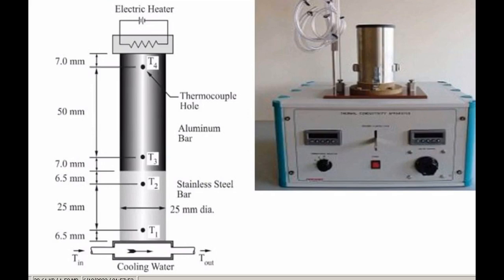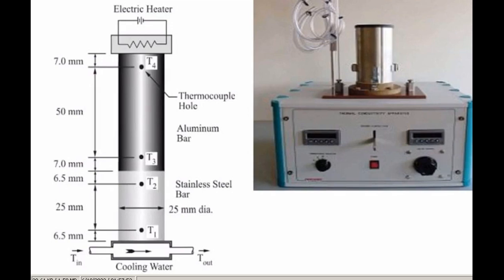That water is taken away from the water outlet line. So at the very first attempt, we operate the water outlet line fully open, without regulating that valve. In that manner we measure the time taken to collect 200 milliliters of water from the water outlet line at the very first attempt.